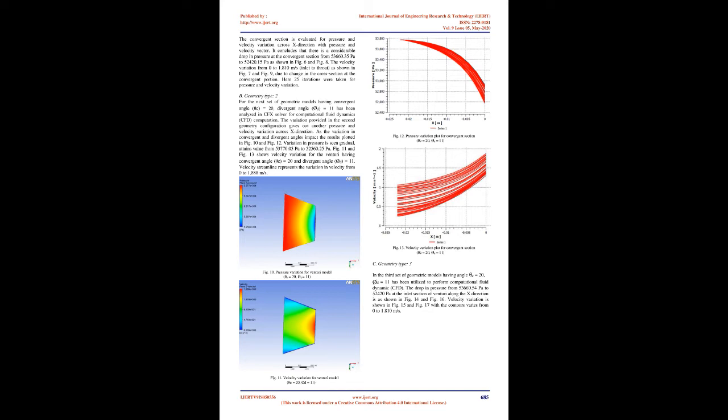To control the flow through both pipeline flow control valve has been placed at the inlet and outlet of a pipeline. In this setup, the pipeline of 40 mm diameter was used to perform the experiments. According to that, the Venturi installed on the same pipeline. By opening and closing the flow control valve which gives the manometric reading using U-tube differential manometer, the water was collected in the water collection tank for the 100 mm rise of water level in the corresponding tank. The area of pressurized water collection tank was 0.036 square meters. The flow rate for fluid flow is varied as per procedures followed.